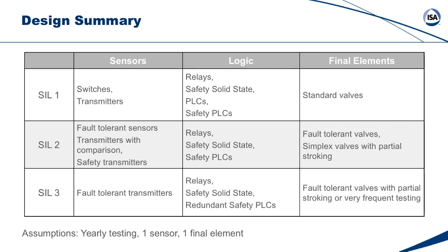The valves tend to get very difficult now. This is where a lot of expense comes in. There have been people that have implemented 3 valves in series, or 2 valves with quarterly testing, or 2 valves with partial stroking. A single valve is very, very unlikely to meet SIL 3, no matter what the vendor might say, no matter what their certificate might say from the assessor based on failure rate. If you understand the numbers you're looking at, you'll realize how, I'll just say, unbelievable certain data and certain certificates are. So be leery and cautious of what certain vendors may say.